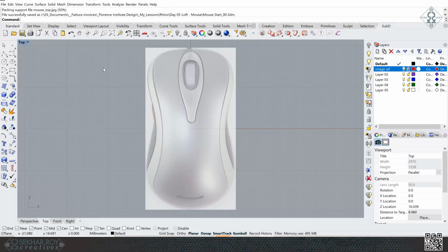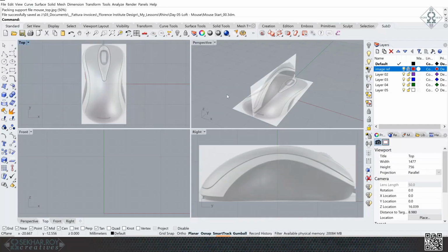So what we need basically in this creation method, we're going to use Loft. So I'm going to draw some lines here. So we got our first curve, which is this one here. We're going to draw this, that's our first curve. We're going to mirror this from this center, so we get this side. Okay, so that's the mirrored plane.